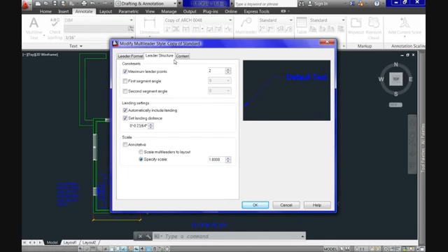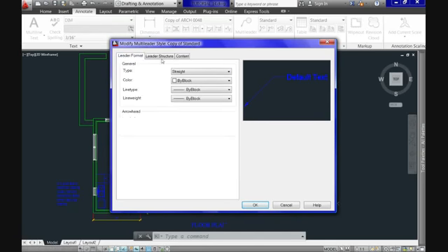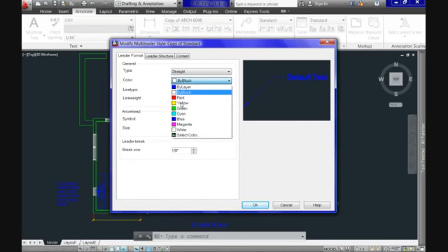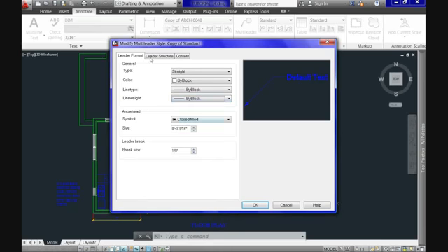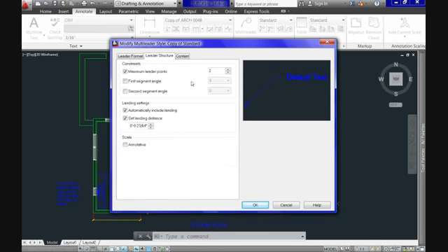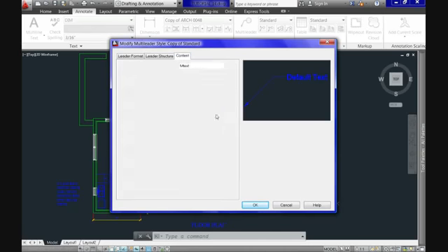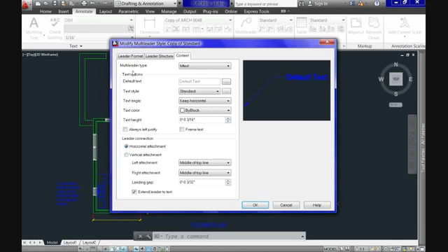The Leader Format tab basically will give you the ability to define your leader in terms of color, line type, line weight, size, type of arrowhead or tip, etc. In the second, Structure, you can give specifications for the scale, the constraints, and the landing settings for the leader. And in the Content tab is where you'll find more options. These are related to the appearance of the leader in terms of the style, the color, angle, height, and or justification for the text to be used itself.